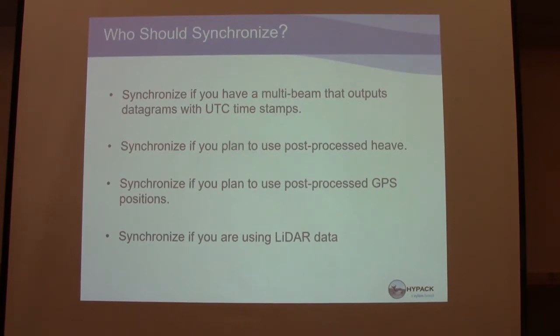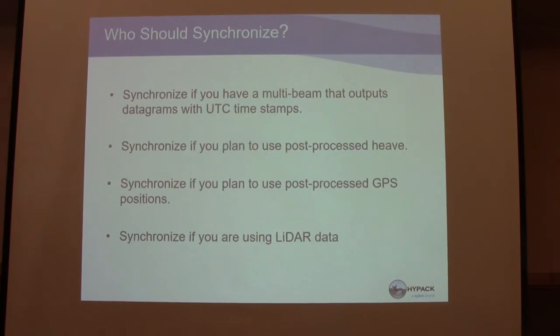So the first thing that I do when I get on the boat is look at what equipment's being used, the positioning device, the heading device, and the sonar, check out the offsets, and make sure that I can look around the boat and see where everything is located, and then look at HYPACK hardware to make sure it makes sense and everything's in the right spot.